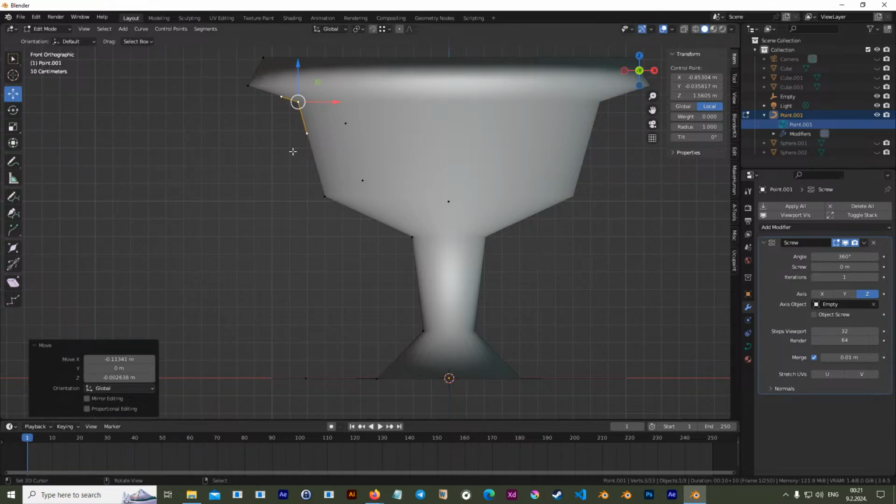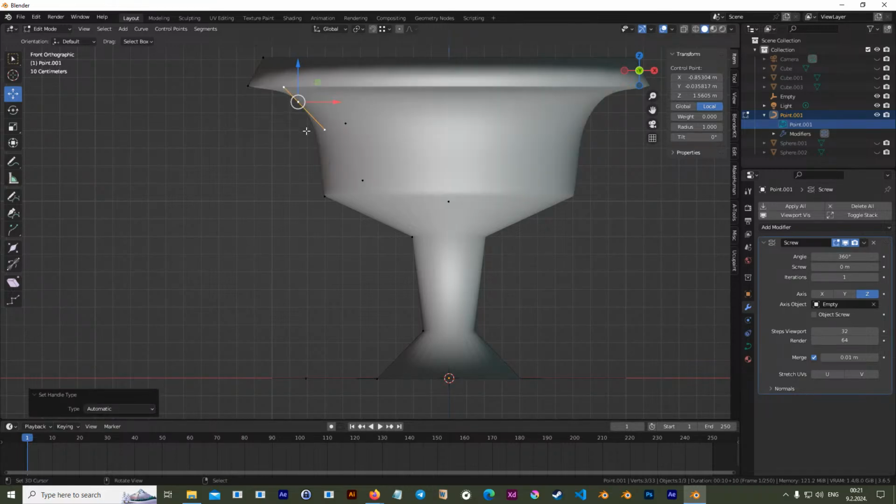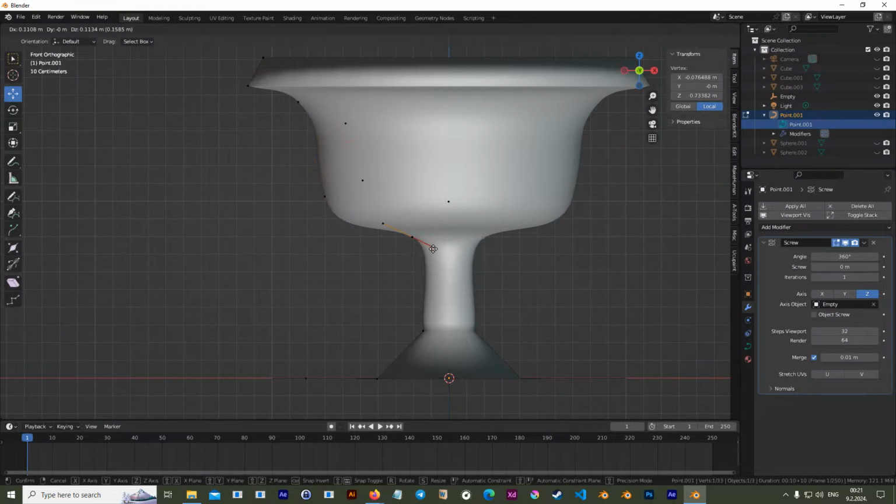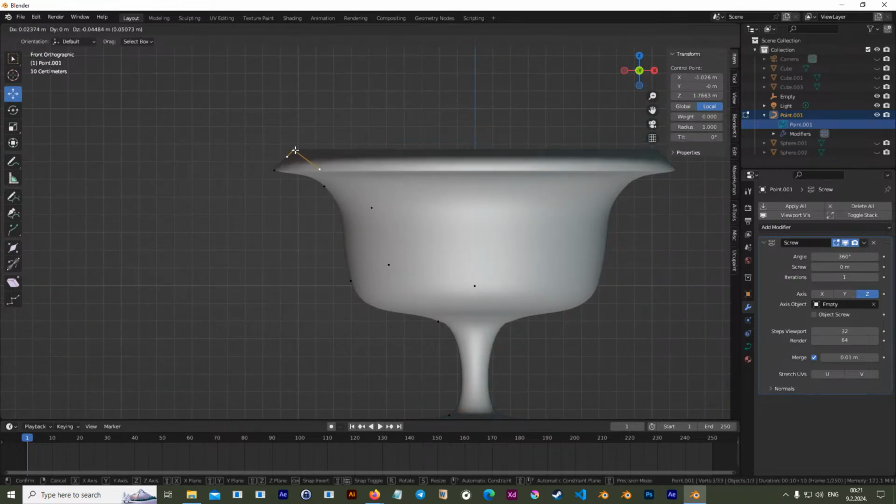It's a good thing to learn, to work with 2D lines, with curves inside Blender, and usual commands are V to control your handle to be automatic. You can also control it by your hand. Like this.